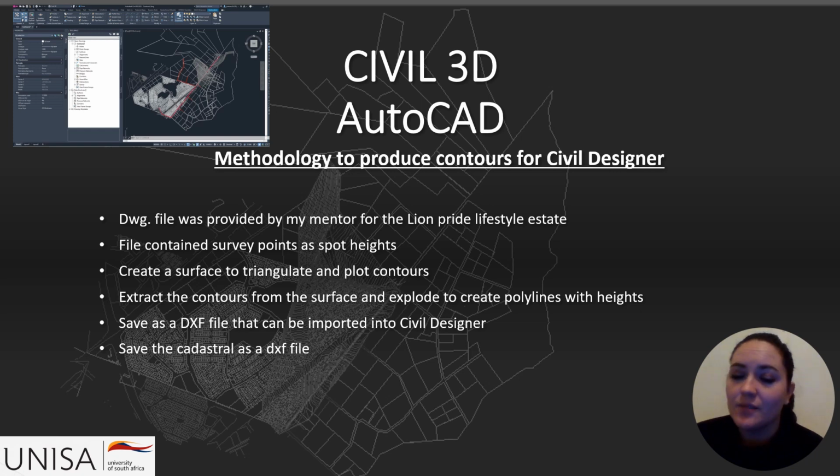Okay, using Civil 3D, which is an AutoCAD software, the methodology was that a DWG file was provided by my mentor. It was for the Lime Pride Lifestyle Estate. Using this file, there was the cadastral, which was already provided, as well as the survey points, which was demonstrated as spot heights. Using these points, the procedure was to create a surface. The surface then can create the natural ground level, which produces contour lines through triangulation. Using this, you can plot all the contours for that area from the spot heights.